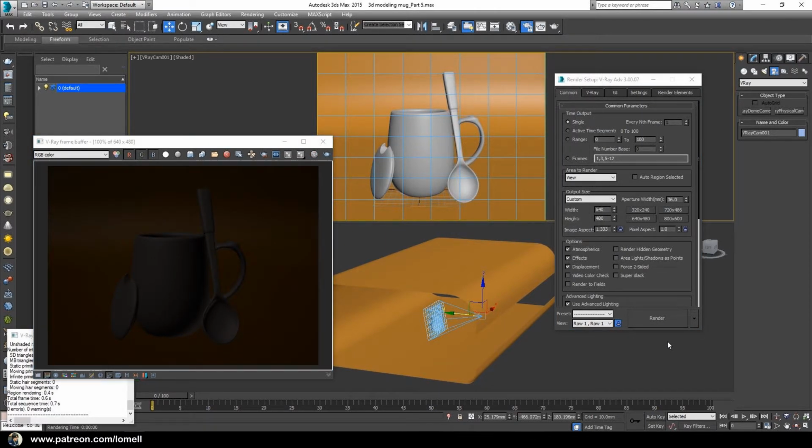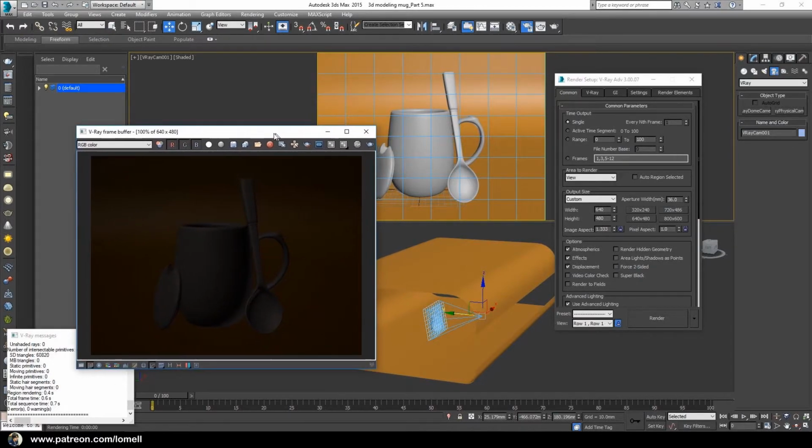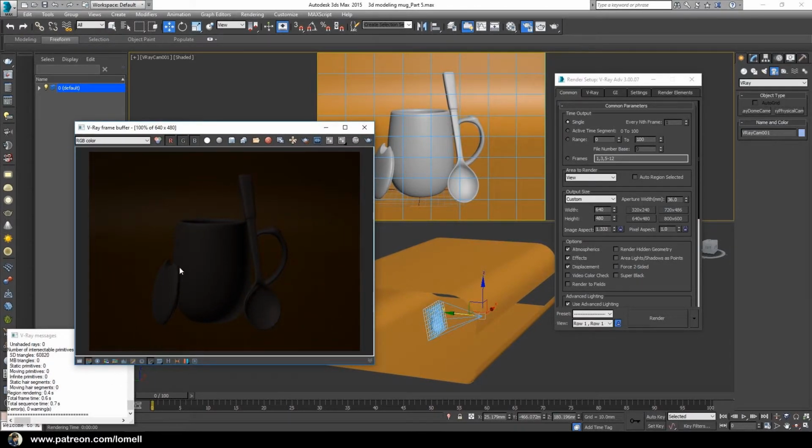Okay, so the next thing we need to do is to expand the pixels of this frame buffer. So we are currently rendering in 640 times 480 pixels. So under command tab in the output size group, let's lock the aspect ratio. Click that lock, and in width let's enter a value of 1500 pixels, and of course the height will instantly follow as we change the value of this width because we already locked up the aspect ratio. Okay, now I'm gonna close this one.